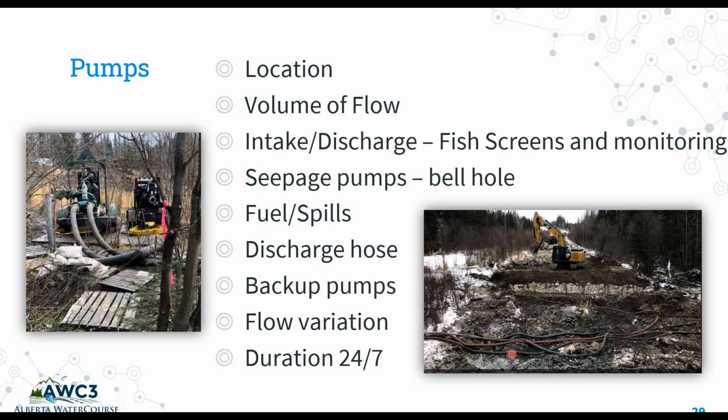Discharge hose: where are you placing your discharge hose compared to your excavation? So you're not blocking access from equipment coming to site. Backup pumps. There are 2 reasons for backup pumps. Number 1, what if one of your pumps breaks down? So you need to have your backup pumps to handle water flow for that purpose.